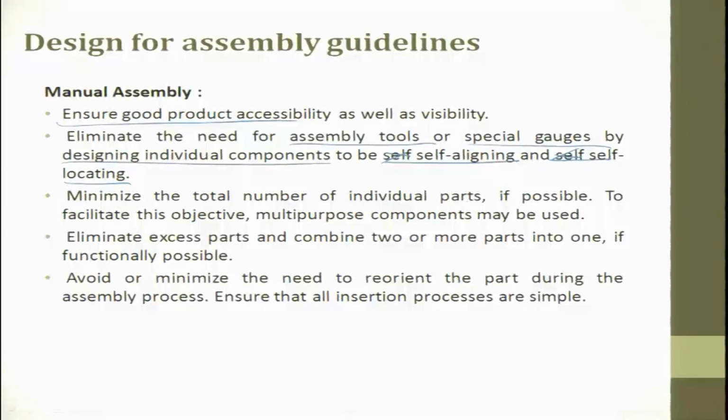Minimize the total number of individual parts if possible. To facilitate this objective, multi-purpose components can be used. So eliminate excess parts and combine 2 or more parts into one, if functionally possible. So here what they say is, instead of having a shaft, then a hole, then a projecting shaft,